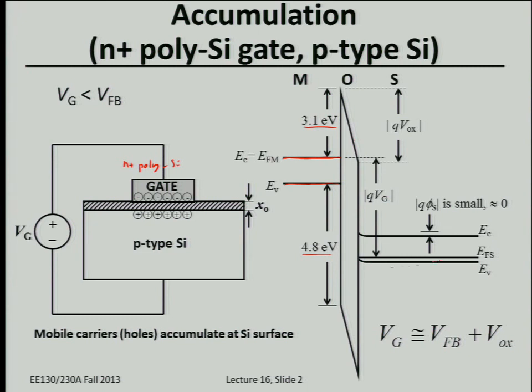Now, an interesting key point, this is an approximation, but the Fermi level in the silicon is close to the valence band edge, right, because it's p-type. So if you have energy band bending in the direction corresponding to this gate bias polarity, basically we know that the surface is going to be accumulated, so the energy band is going to bend up.